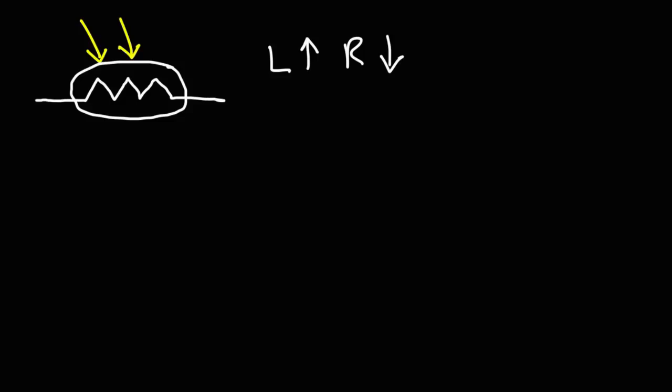For one example, you can create a night activated switch. This is a video on YouTube that I've created, if you want to search it out. It's called Night Activated LDR Sensor Circuit. And what it does is if you turn off the light, the circuit causes the LED to be activated. The light emitting diode begins to shine when it's dark.